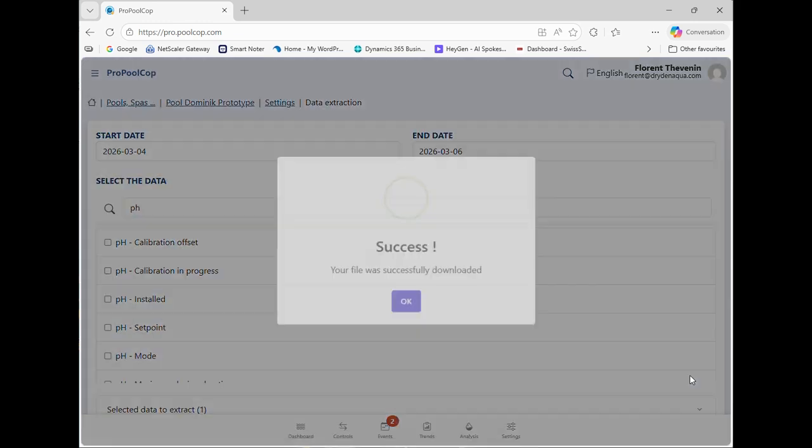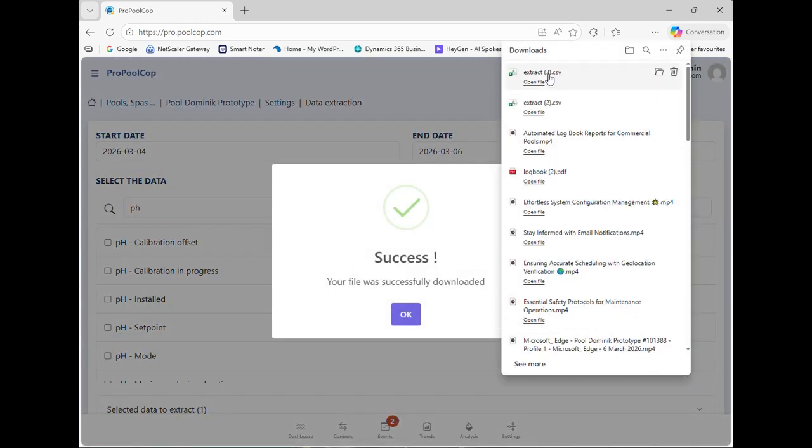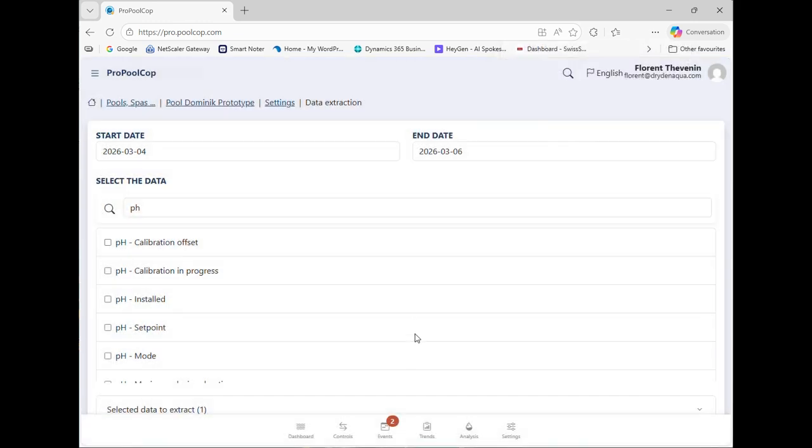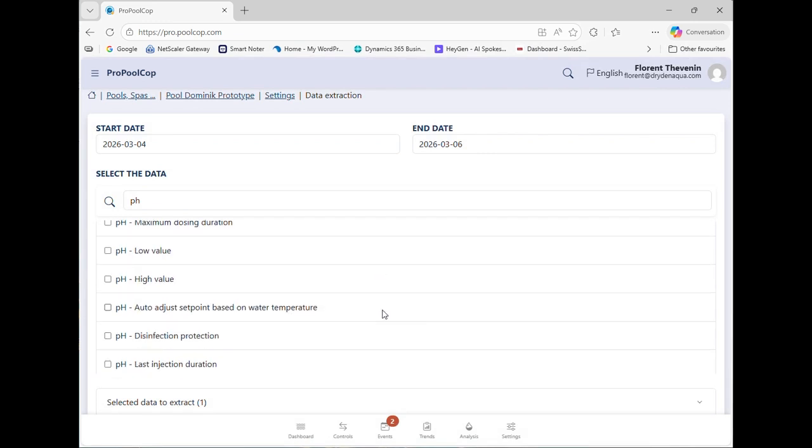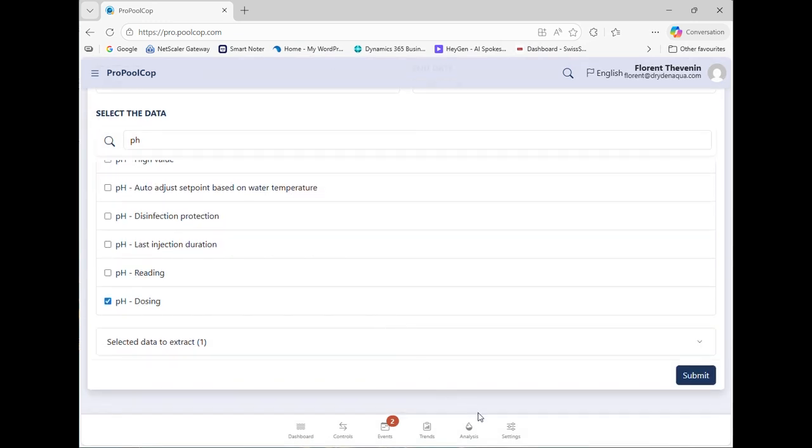You can analyze heating system runtime, chlorine dosing duration, chemical consumption, pump operation time. For example, by combining dosing, pump flow rate, and runtime duration, you can accurately calculate seasonal chemical consumption. This tool provides full operational transparency and advanced diagnostics.